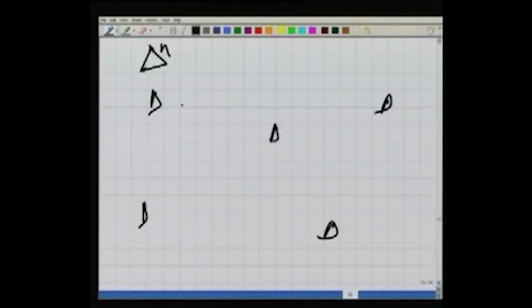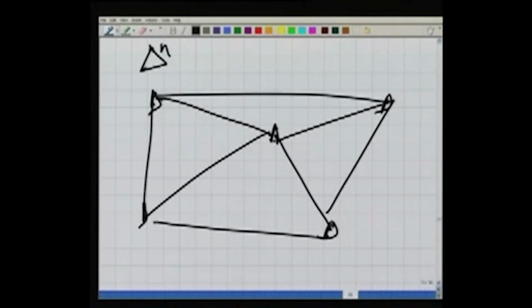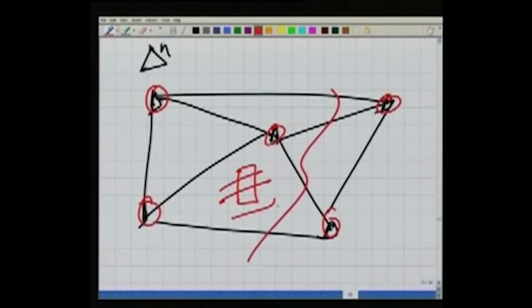As we will see later on when we talk about plane tabling, how we can make use of these coordinates in plane tabling. Because in plane tabling, we will make use of this network. Let's say there is a big network here, and these distances are of the order of 1 kilometer. Now I want to make the map here. I want to fill the details in my map, because so far in my drawing sheet, I have only these stations plotted, nothing else. Now I want to plot the other things, where the roads are, where the houses are. I want to plot everything.